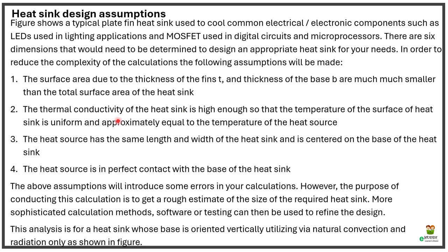The second point is that the thermal conductivity of the heat sink is high enough so that the temperature of the surface of the heat sink is uniform and approximately equal to the temperature of the heat source. So we are considering equal temperature and heat distribution. We are not considering any hotspot. Then the third assumption is that the heat source has the same length and width as the heat sink and is centered on the base of the heat sink.